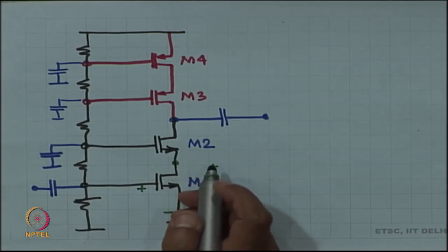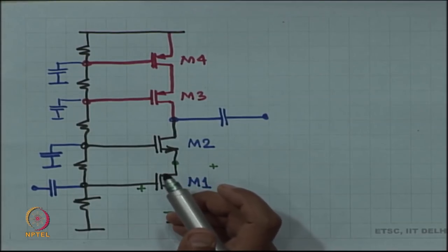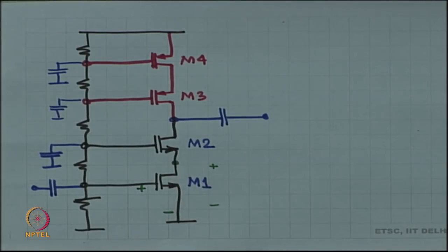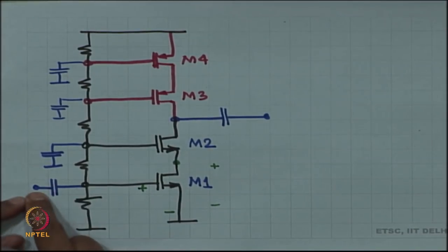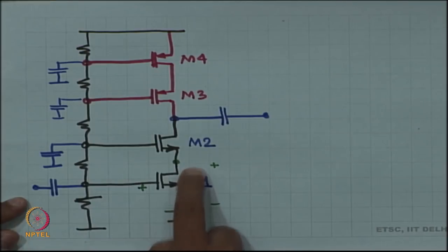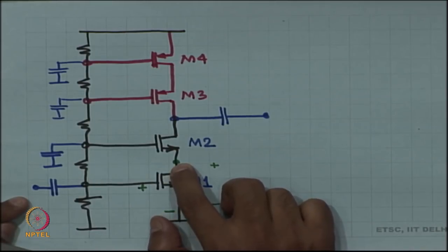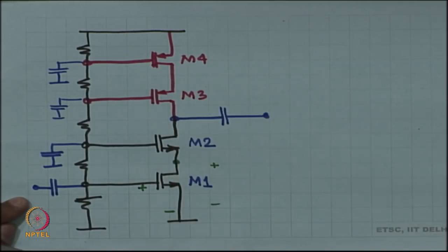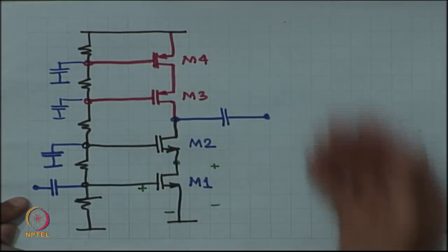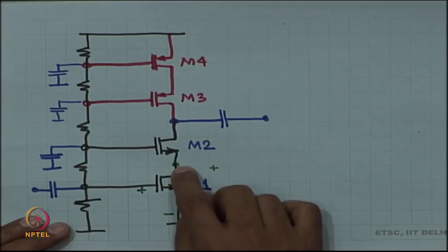If you have a given current amplitude and the impedance is low, then the voltage amplitude is going to be small. You apply a signal, gm1 times the signal is the amplitude of the signal current through M1. This signal current is seeing a certain impedance at this node, the Thevenin equivalent impedance of the rest of the circuit, and that creates a voltage at this node.